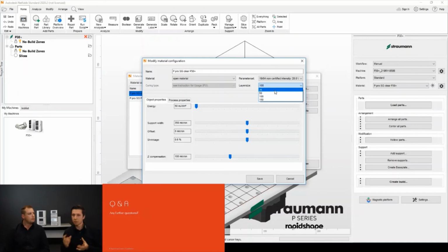So if you're printing with 60 to 70 microns in X and Y, the quality in X and Y will always stay the same. Yes. So the Z-axis is going below the quality. The general quality of your part will never be way better than the lowest quality you can achieve, in this case the X and Y resolution. So it's really not making any sense to go below this if the printer has an X and Y resolution of a little bit bigger than 25 microns.